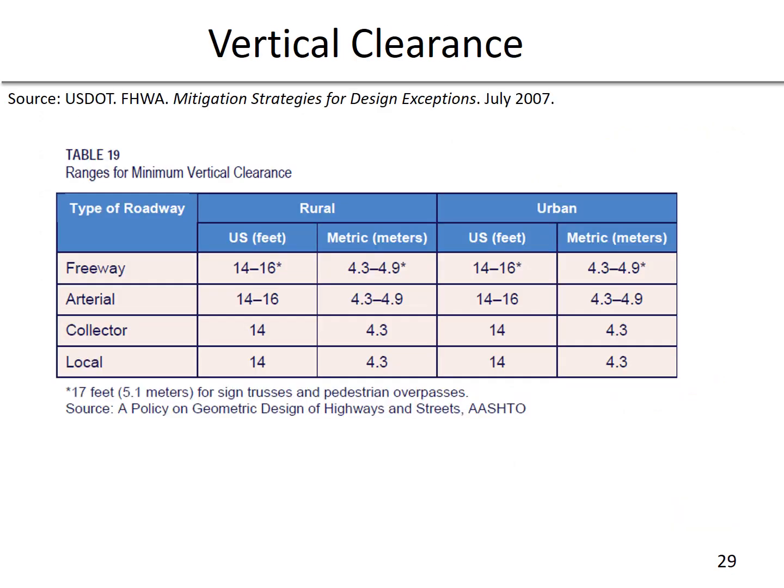Vertical clearance is a very important component, particularly of our national highway system. These are the adopted criteria for various highway functional classifications, and these are used to provide at least a 1 foot differential between the maximum legal vehicle height and the roadway itself. We've got to think about additional allowances for resurfacing.